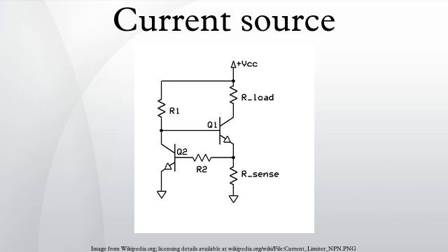A real-world current source has a very high, but finite output impedance. In the case of transistor current sources, impedances of a few megohms are typical. An ideal current source cannot be connected to an ideal open circuit because this would create the paradox of running a constant, non-zero current through an element with a defined zero current.